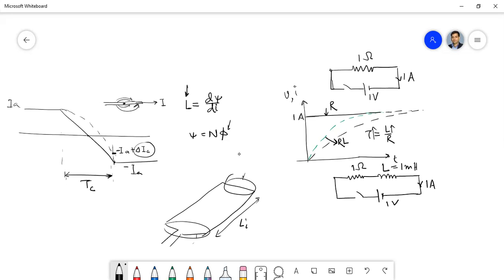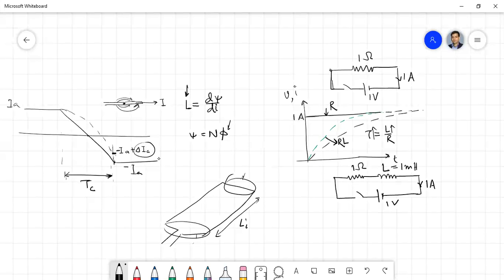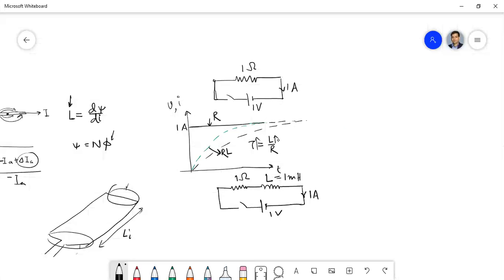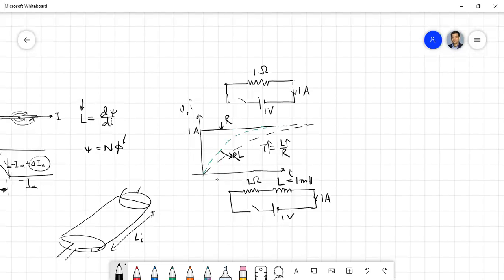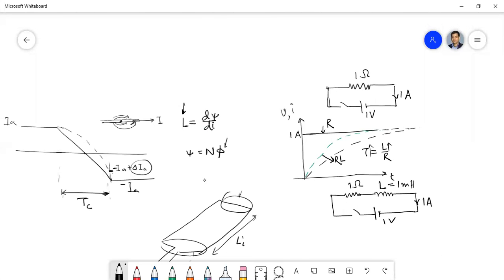Not only that, the flux through which the coil undergoing commutation is passing also contributes to the inductance value. Now, from this circuit, we can say if the inductance value is increased, there will be more delay in the commutation, isn't it? And if there is more delay in the commutation, then the amount of spark and arc will be increased, that I have already discussed.